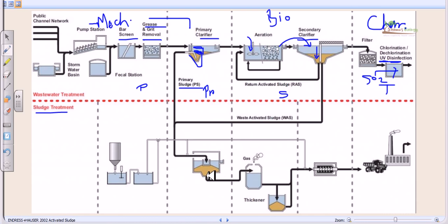Now what we mean by sludge digestion is that we have huge pipes and pumps. We utilize heat, and we utilize a few bacteria which are present in the sludge to digest the sludge anaerobically, and as a result of this anaerobic digestion, they produce methane gas. Now in this particular process, we can utilize a small amount of microorganisms which are methanogens. Now we know the action of methanogens, that they can utilize carbon sources and generate methane gas.